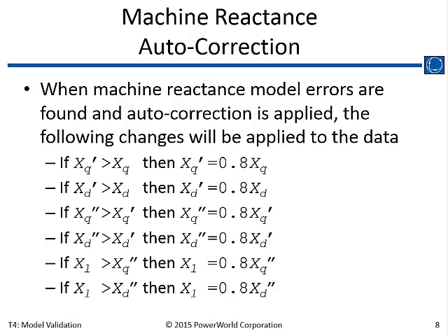If this duplicates, at least this part with the transient and subtransient reactances, what PSLF does, in theory, with the posted WECC cases, there are 2 folders for each case. One folder ends with an E, and they're exporting to EPC format for the data, and they are exporting the DYD format after the fixed bad data is clicked in PSLF.